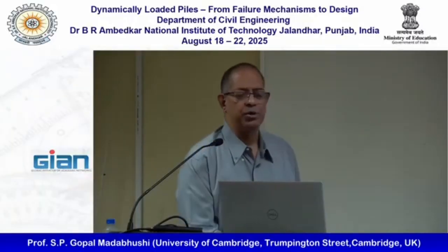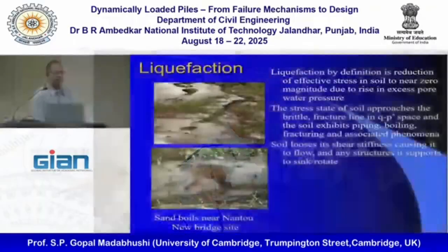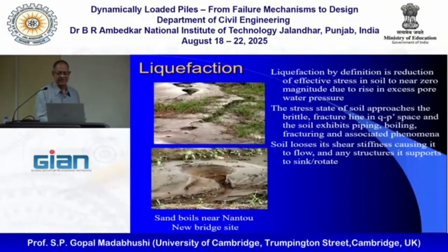Typically, this is a good problem to look at: liquefaction of ground. We talked about this yesterday already, so I'm not going to go into the details. Basically, what we are saying is the soil will lose its effective stress almost to zero as the excess pore pressures build up. And the excess pore pressures build up because you're trying to shake the soil. It wants to change its volume, but there's no time for the water within the soil to escape. You can actually do this in the q-p plane. I don't know if you use this framework.